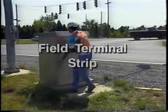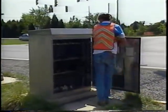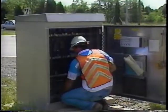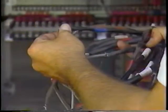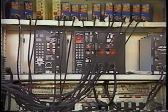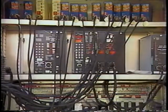Most manufacturers recommend grounding the cable at the cabinet. This entails connecting the shield to the terminal and insulating the end of the cable in the pull box. This allows any electrical disturbance or interference to be safely grounded without affecting the loop lead-in cable. For example, loops receive a voltage surge whenever lightning hits the ground nearby. Back-to-back Zener diodes or metal oxide varistors usually provide adequate protection from these surges.